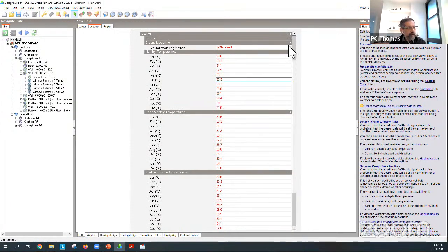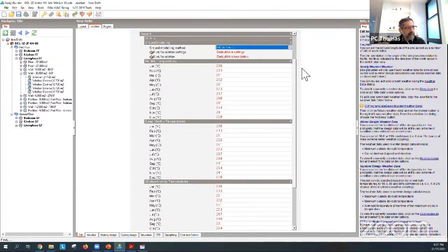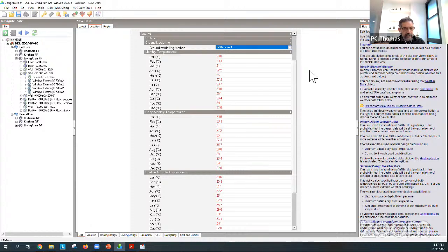Now there is a model that EnergyPlus has incorporated called Kiva, and Kiva Basic actually does provide the best outcomes, but it's still not there yet. So you might have to use the standard and make a little bit of a change. What I did, because I thought I should do something, otherwise the differences are too big, is I looked at the weather file.